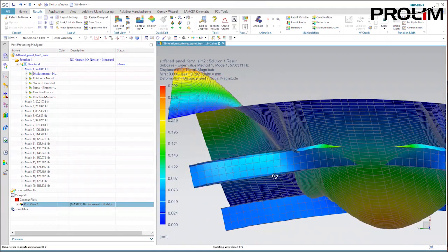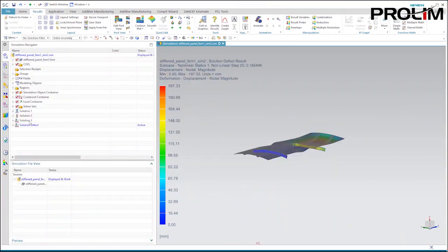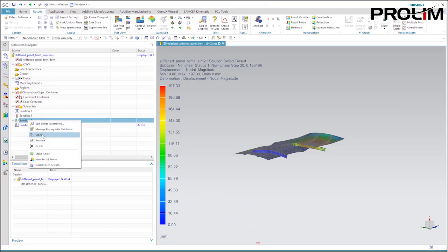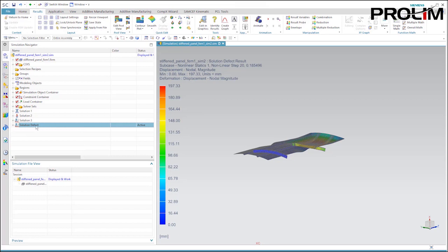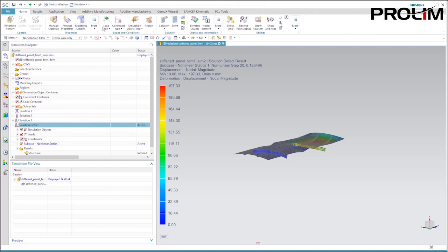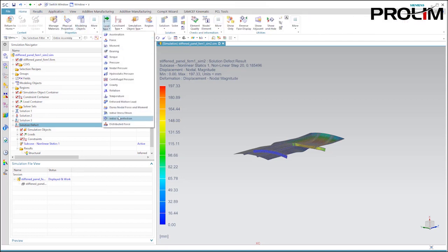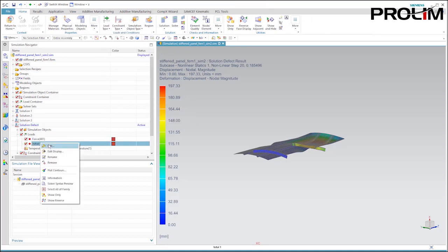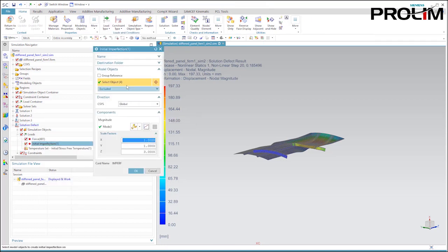So, as a second step, we'll restart Simcenter Nastran Solve 401 and select the proper mode as geometrical imperfection. We run the post-buckling analysis again and end up with a slightly different path compared to the one calculated without considering any geometrical imperfection.